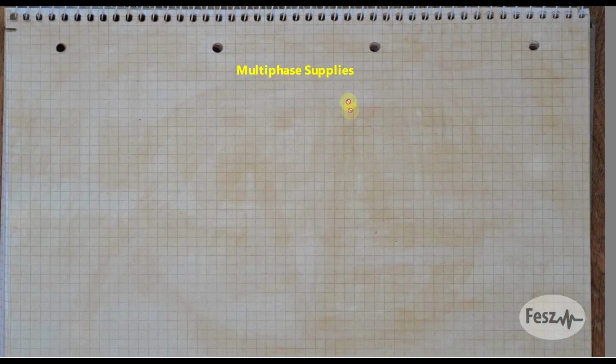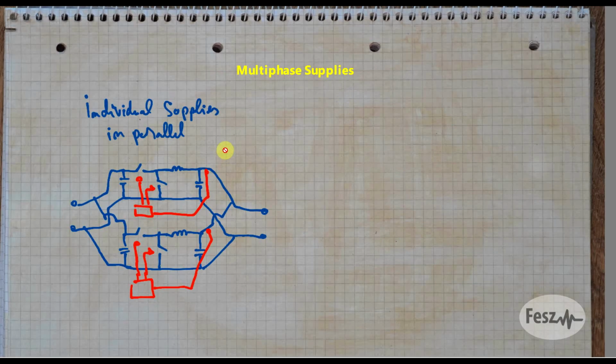Now, once you're familiar with the basic single output topologies, you can start complicating things by combining multiple pieces of the same or combining different topologies to get various benefits and headaches. First thing to mention is multiphasing. So usually when large currents are involved, it's helpful to put multiple converters in parallel. Now, this is not always the best idea, since if you have individual control circuits, they will give slightly different output voltages, and then you won't really have equal currents running through your parallel converters.